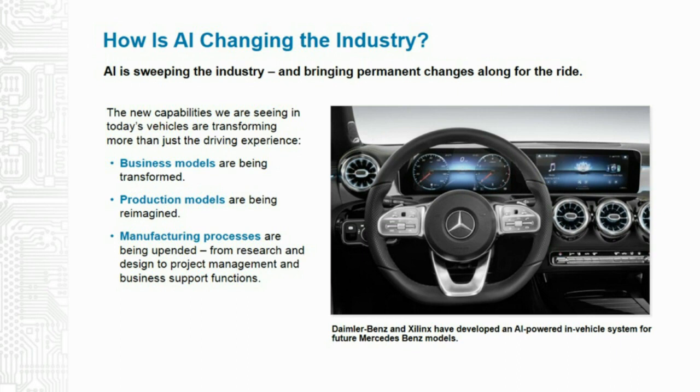What an AI algorithm does in this case is digest the masses of data from vibration sensors and other sources. It detects anomalies. It separates errors from background noise, diagnoses the problem, and predicts if a breakdown is likely or imminent. And you'll be hearing a lot on the manufacturing and the Industry 4.0 side about predictive maintenance. I'm saying, look, this is likely to happen in the next time period, and it gives the people on the maintenance side an opportunity to either fix it before it breaks or to be better prepared for a breakdown should one occur.